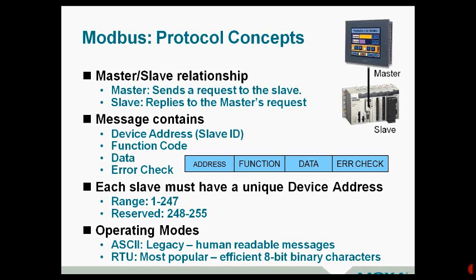It may default to one from the factory, and based on your application, you may use that, or you may reassign that as you configure your specific application. So that is a number that ranges between 1 and 127, and please be sure not to use addresses 248 through 255 because these are reserved, and there are some special uses within some types of software, and you don't want to use those for your application.